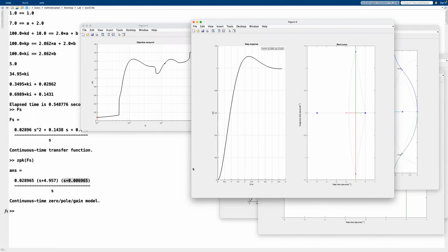And it doesn't actually take that long if you think about it, and if you come up with this result or conclusion. If you can conclude that the best controller is going to be canceling out this pole here and not using a PID controller, but a PD controller, then you just get rid of this one here. You can just use the gain condition and come up with the overshoot value that you're looking for. So the distance from here, of course, the angle condition and gain condition in conjunction. If you're in an exam, you should just spot this valuable result here. Other than that, calculating it would not be that difficult if you know what you're doing.